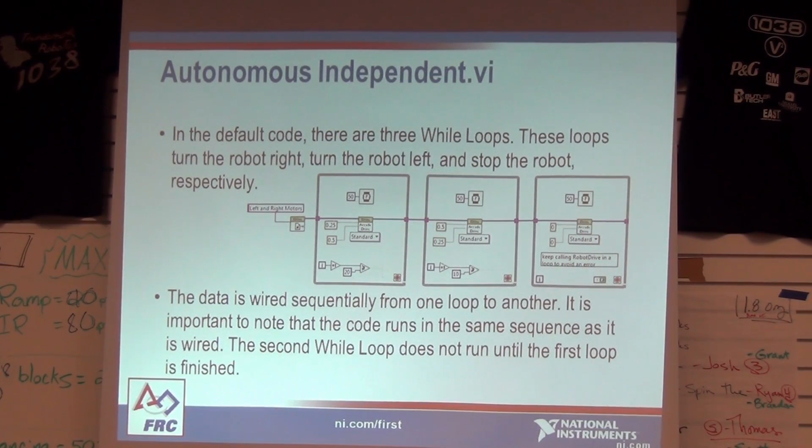So what this is showing is a get right here. I've set it in Begin, and now I'm doing a get, and I'm using that same name, left and right motors. What I get out is that cluster that I set in Begin. And so when I get my left and right motors, now I have access to these drive VIs to be able to utilize the data, those PWM references that I opened in Begin.